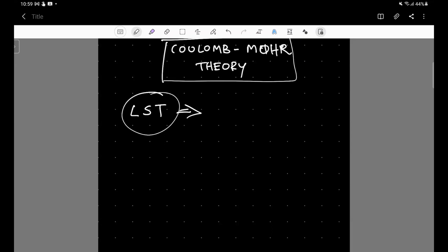It is not simply clicking buttons, but making sure that you are in control of the simulation. That is, you define a certain mesh, you apply certain boundary conditions, and you analyze the results with a clear idea, without directly accepting the results provided by the computer.